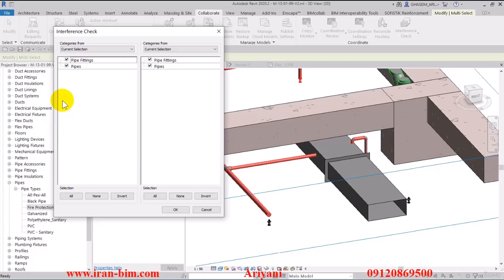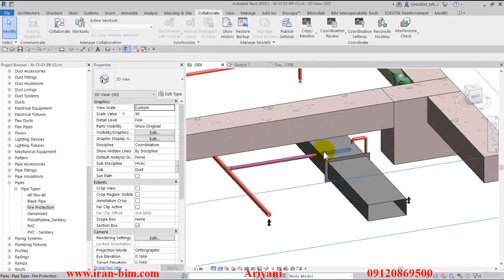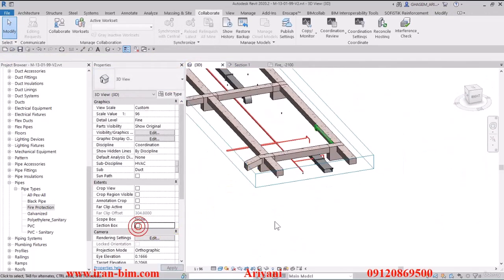So it doesn't recognize ducts. So keep in mind that if you use the fabrication tool in the Revit file, either in the ducts or in the pipes themselves, it doesn't recognize the clashes. Because in this project we've used only ducts, it doesn't recognize them, but the pipes show up here. That's why if you check out the Autodesk site itself, it says you need to analyze the pipe clashes in the Navisworks because the Revit doesn't recognize them. And for example, in structure, it doesn't recognize the collisions of beams, and you'll have to move it to Navisworks.